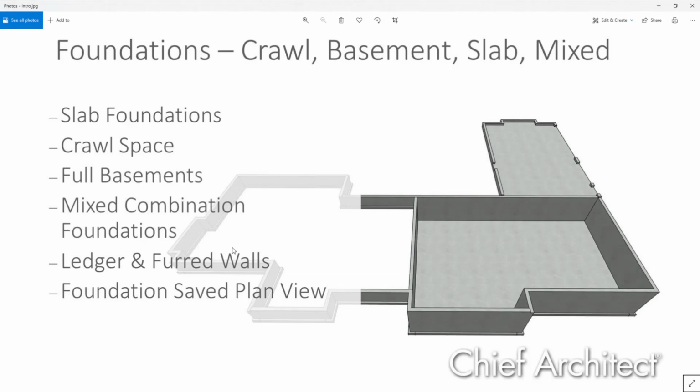Hi, this is Marge from Reed Springs, Missouri. I'm still working on this style house. This intersection is 20 feet wide, and they're going to be load-bearing walls. And when I do the auto foundation, it puts a full stem wall. I have a 48-inch stem wall on top of the footing. And I'm thinking that what you did on those walls earlier, could I take those and change those from the full stem wall to a pier and post?